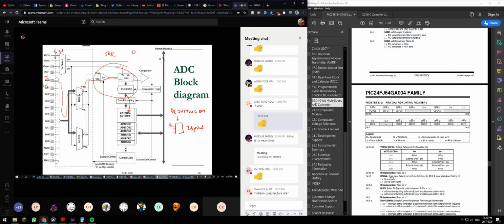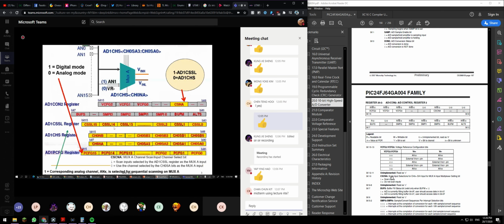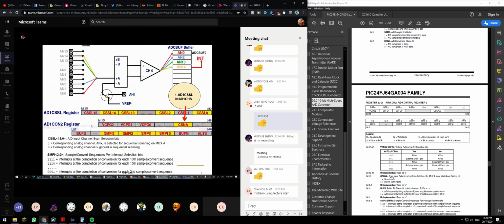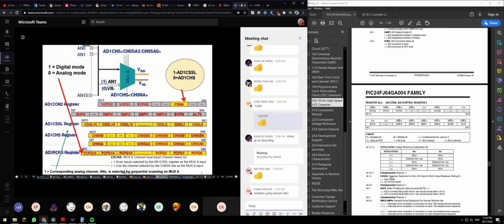Let's say you fully utilize all 12 channels. So you want to do multiplexing for the system to do conversion. In your situation, at most you just use 2 analog digital conversion channels. You're not going to connect 12 or 13 here. Is AN0 to AN12 13 channels, correct or not? If you got 13 only, we're not utilizing these two, we just use up to AN0 until AN12.